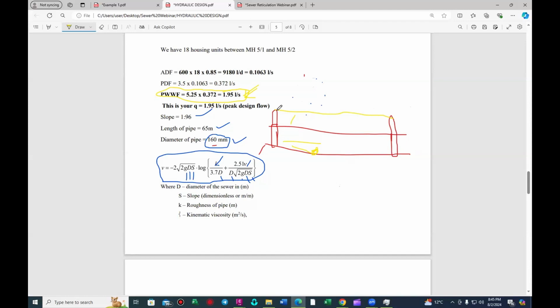So I drop my spoon there, because it's only me doing dishes at that time. There's only little water, so that water does not have enough energy or velocity to push the spoon down or to push the sand down. So the sand is going to gradually collect. Someone drops their soap down the drain, it's going to gradually collect. Then these sediments are going to accumulate like that. As they accumulate, please take note of that, the diameter of that pipe is going to be gradually reduced.